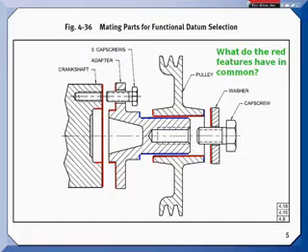In another webinar or another brown bag, we talked about how all parts in space have 6 degrees of freedom. And if I am going to make full contact on this face, that's going to take away 3 of the degrees of freedom, 1 translation and 2 rotations. And then this pilot diameter is going to constrain 2 degrees of freedom, 2 translations. The only thing the adapter will be allowed to do is spin. And once we put the screws in there, that'll stop the spinning. But I don't need to use the holes for the screws as datum features because there isn't anything else to align to those. So on this adapter, we'll see that the face and the pilot diameter have been called out as datum features.